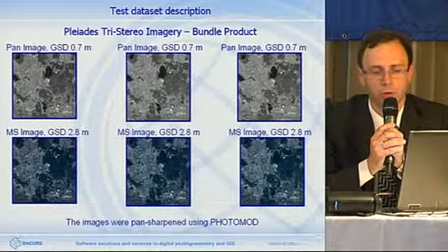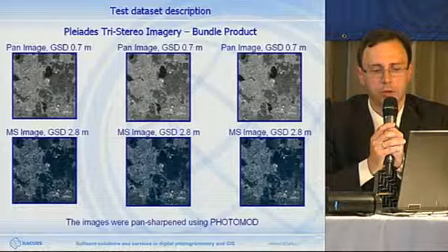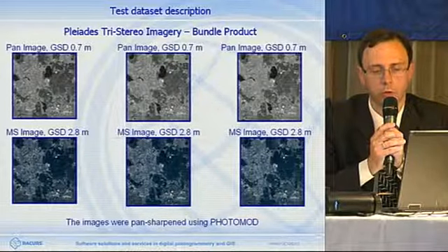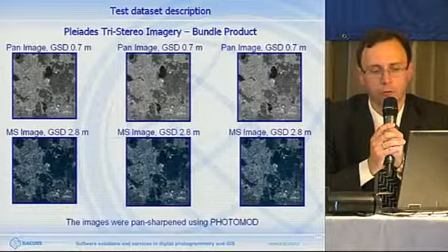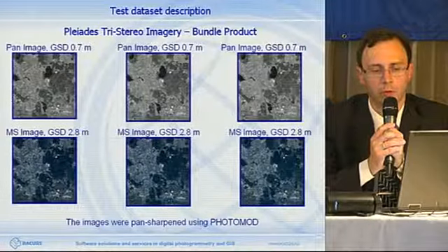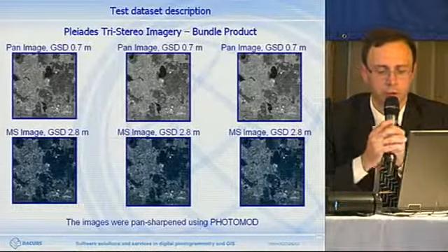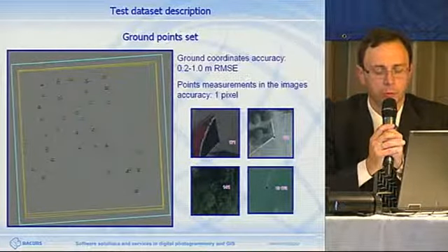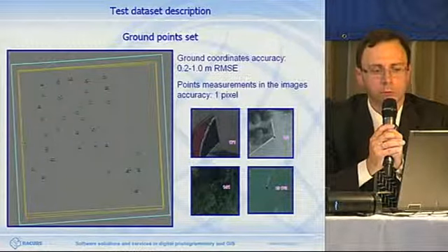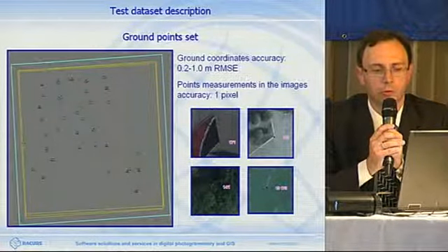To do this project, we also did pan sharpening. Pan sharpening was done at the stage of adding these images to PHOTOMOD. We used PHOTOMOD at the input stage. It's not always possible, unfortunately. Sometimes we have to do orthophoto, do pan sharpening later, but as far as Pleiades are concerned, it's much easier and user-friendly. So it is an easy and labor unintensive work.